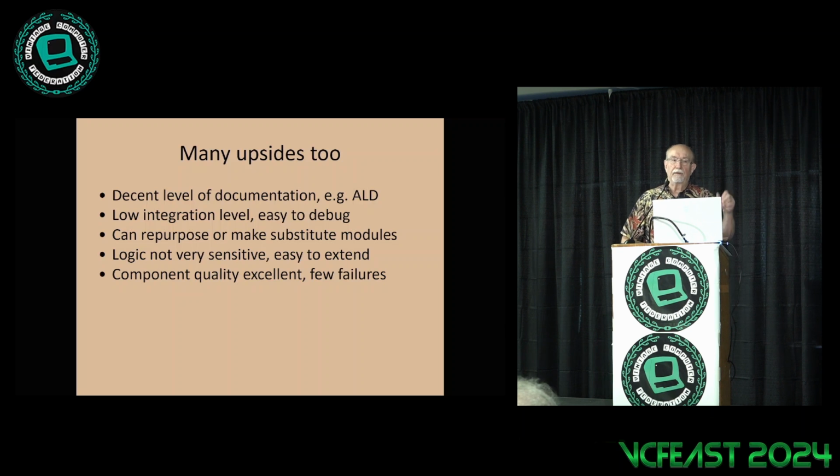And I've seen a couple of electrolytics where the capacity was still fine, but the resistance was getting a little high. So very great products. The resistors are almost spot on their value, 50, 60 years later. So one of the advantages of them is they really picked high quality parts.